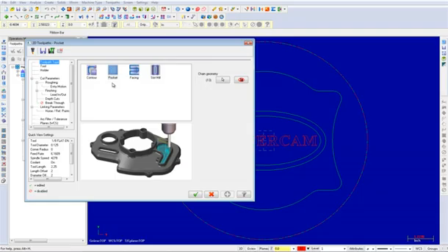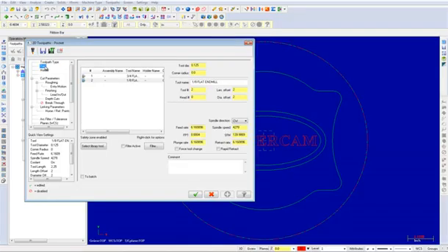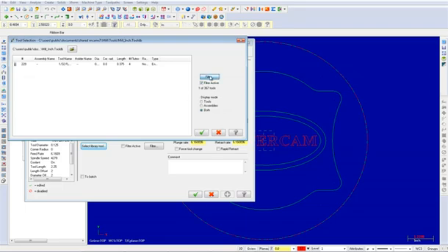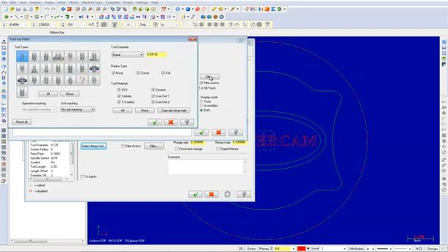To do this, choose Tool from the tree view list. Now, click on the Select Library Tool button and then choose the Filter button. Select the None button and then under Tool Types, choose the flat end mill icon. Under Tool Diameter, pick Equal and input a value of 0.03125. Once the parameters have been adjusted, select the OK button to exit the tool list filter.